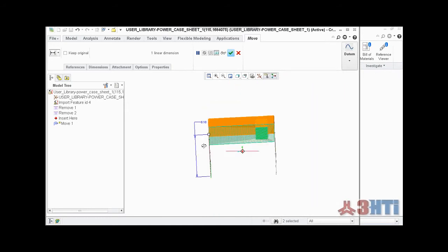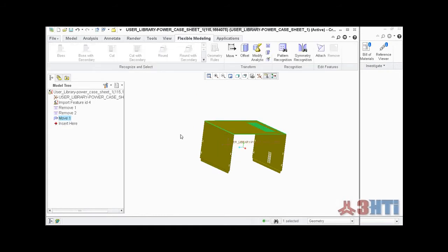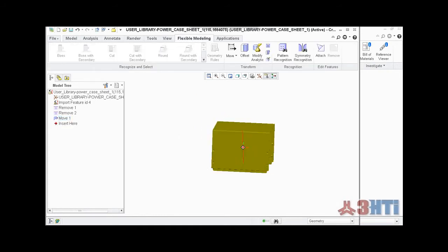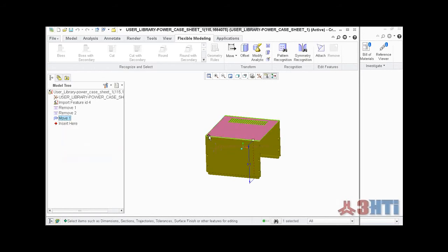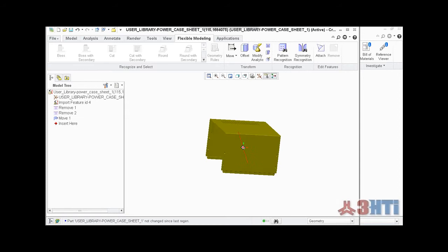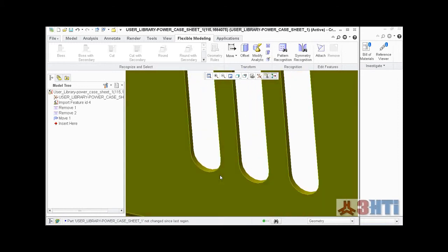So now I've added some height to that particular geometry. I've raised the height of that sheet metal part pretty easily. Okay, if you look at the model tree and you perform an edit, you'll see that there's actually a physical dimension. So later on, you can go in there and change that. So I've taken something that wasn't parametric and given it some parametric capability. Later on, you can actually show that dimension on a drawing, for example, and make all other kinds of changes.